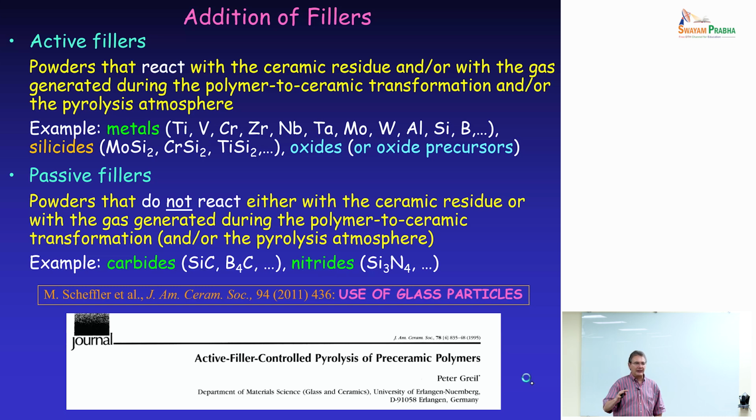You're pyrolyzing in inert atmosphere. This is quite interesting and useful. One of the reasons why this is useful is that you not only generate useful phases like metal carbides, but that also affects the shrinkage in your material, as I will explain in a moment.